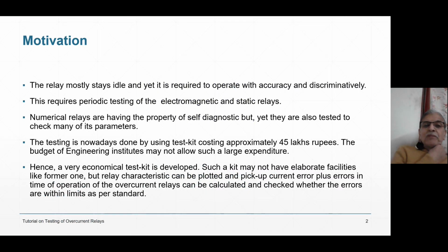Very important thing is, if a meter is not working, you will immediately come to know, because it will go to zero. And if you are seeing the wattmeter, it is showing some power, but current is showing zero, right? You are seeing the voltmeter, voltage is showing, but current is showing zero. Circuit is complete. So you will come to know that the meter is not working.